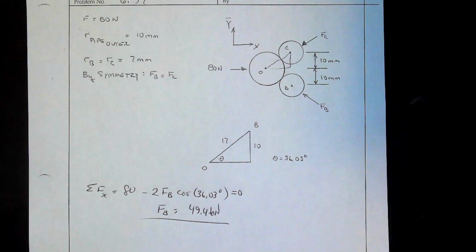All right. So, and how did I draw this? Well, look at this. If this acts as a fulcrum, as this goes down, it means this end is going to want to go up. So EY obviously has to be pushing down this way, or this thing has to be pulling it down. And if this is a little to the left, that's got to be to the right. So that's the logic behind why I drew what I drew. But this is definitely a case, no big deal. If you put EY up, so what? The signs actually will work for you. You'll get a negative and it will be fine.